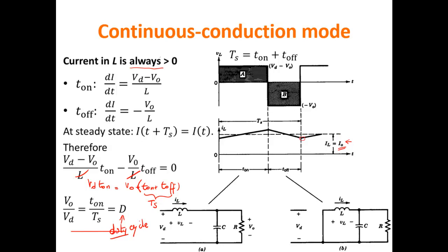Imagine we reduce the average current going to the load, which can happen because the load can change its power requirements. You can switch off a loudspeaker, for example, and then require a lot less power. Then this point can go down below 0, and that is something that needs to be taken into account, because otherwise it is going to degrade the operation of the circuit.